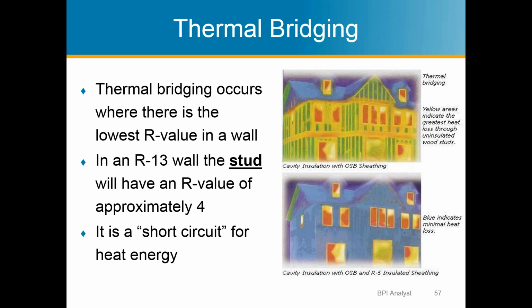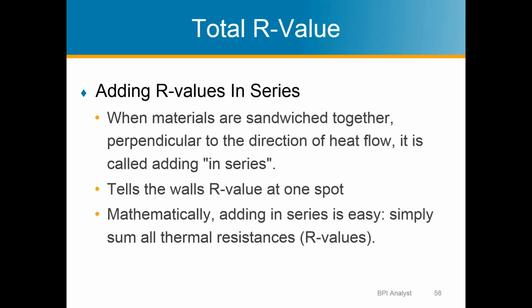So there's talk about thermal bridging, and that's when we talk about continuous exterior insulation. We would put in styrofoam insulation on the exterior of the building on top of the studs, and it just would help add insulation on top of the wood and the cavity, the R13. So it increases dramatically the R value of the whole wall assembly. R values can be added together, and U values cannot.